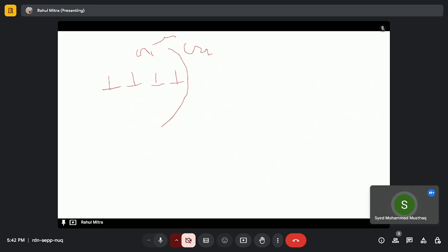For example, if in grain 1 we have 100 planes facing this direction, in grain 2 we have 100 planes facing another direction. So for the dislocation to move from grain 1 to grain 2, the grain boundary has to start deforming to accommodate and move these dislocations.